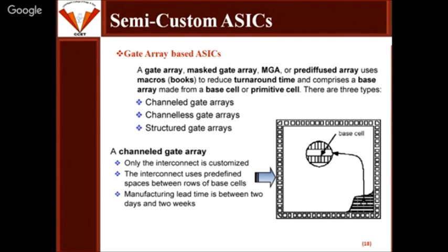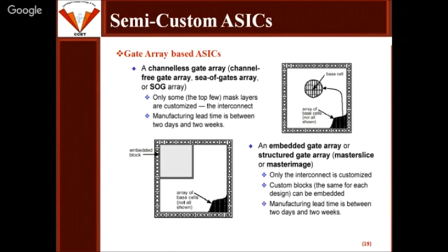At the same time you will find another one, which is the channel-less gate array. The point is that we are not defining any channel in this case. We are only placing the devices, and wherever we get the routing part, we get some space. We are just channelizing our interconnections and making the interconnections. So it is also termed as channel-free gate array, sea of gates array, or SOG.